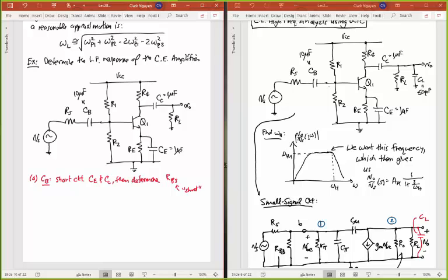Okay, same procedure. I'm going to replace CB by a test voltage source. So just looking up here, there's my test voltage source, plus minus there. On this side, I'm going to have a resistor, and I'm going to ground out my source like I said we would. This is now going to go into that parallel combination of R's, which I called RB before. So I'll call it RB here. I guess I could have just written out R1, R2. And then the rest of the transistor equivalent circuit. So I'm going to have an R pi here. I'll have my VBE right here.